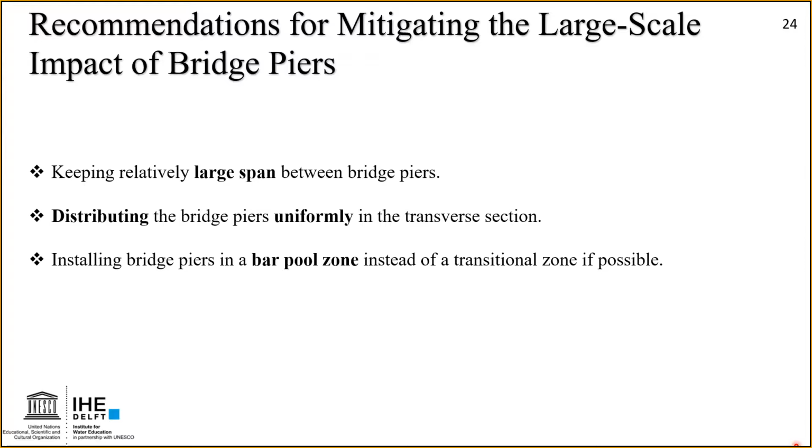Also, installing bridge piers in the bar-pool zone has some problems, because when you install them like this, you have to put some piers on the pool side, which is very deep and requires a very deep foundation, and also makes it more vulnerable to scouring.